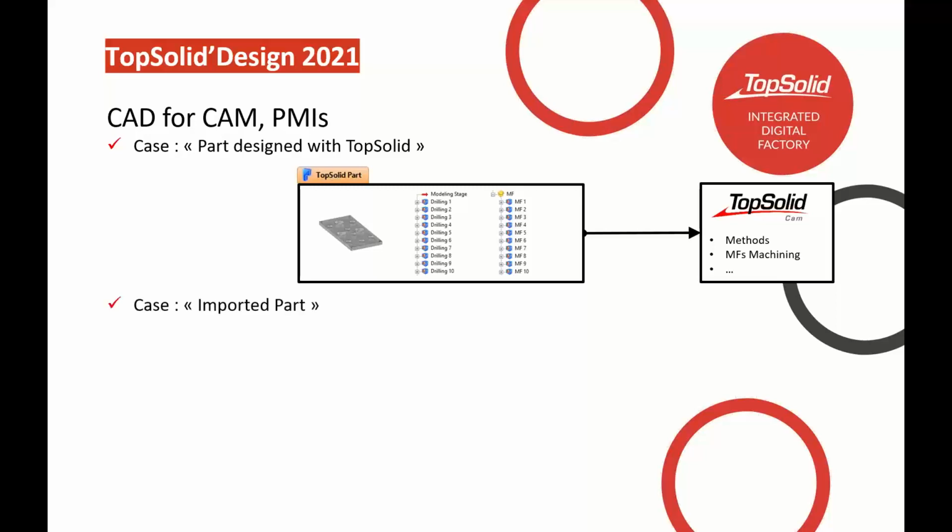What happens when you import a part? So typically when you import a part, you don't have any product manufacturing information. You just have a dumb model. So then you have to use a cylinder analysis command to try to find these drillings, and you have to look at your part print in order to analyze, okay, well, this is actually a reamed hole, so I got to make sure that I tell TopSolid that that's a reamed hole, or it's a tapped hole, or this hole or that hole, okay?